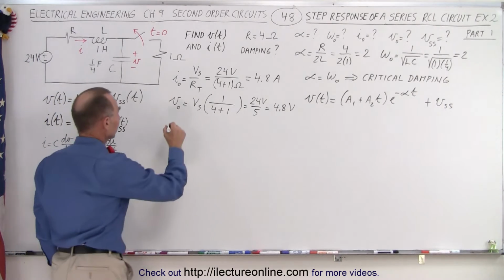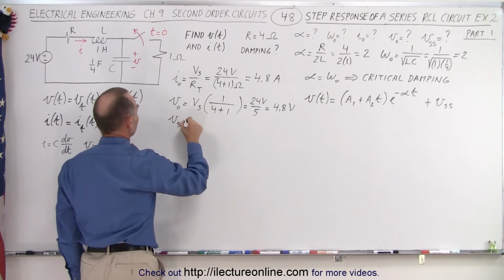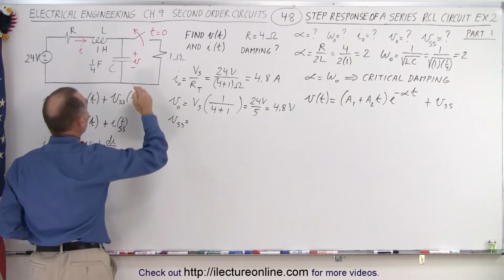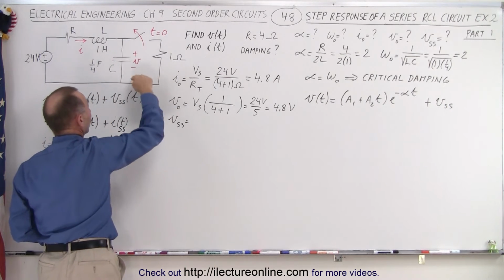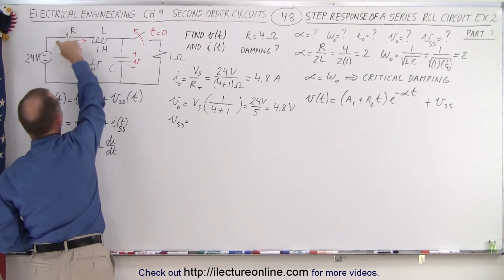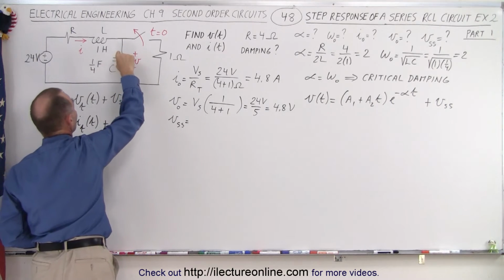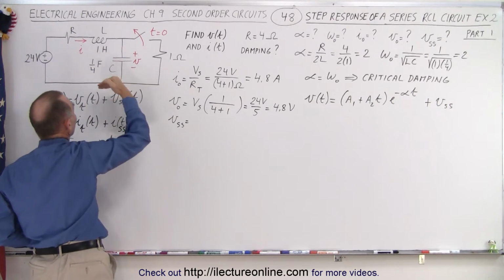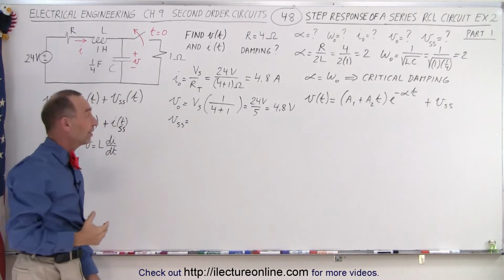How about the steady state voltage? All right, once the switch is open, no current will flow to this resistor. The current will not flow through this circuit, but there's a capacitor here, and it's a series circuit. So eventually the capacitor will fill up.